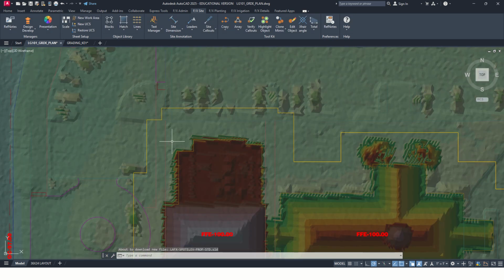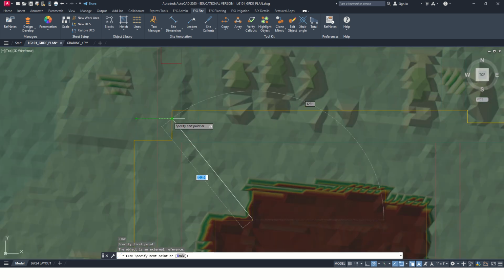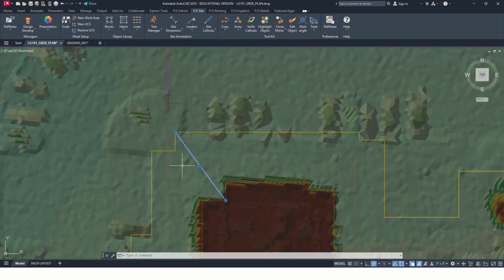And then add it, or you can do the math first. But what you're gonna do is you're gonna have to draw a line from here to, let's say right here, and that line for me is, where's my properties? 34 feet at 2%, okay? And so you just multiply those two together.